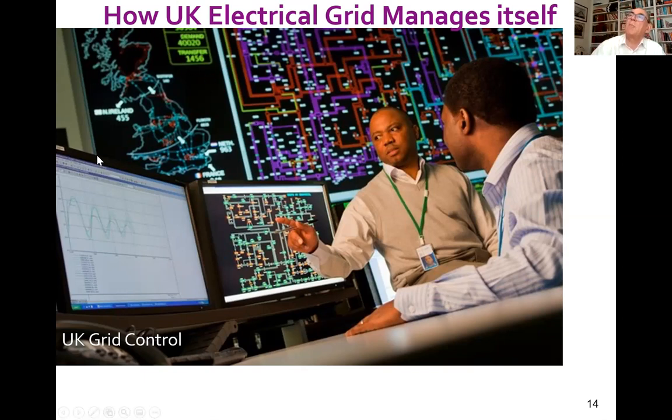And over here is a map showing Great Britain and the power flow. You can't read the number at the top there, but the green at the top is telling me the generation, and I can read it, and it's 39,000 megawatts, 39 gigawatts, being generated. But underneath in green, I think you can possibly read that, the demand is 40,000 megawatts. So the demand is bigger than the generation. So underneath you can see it says transfer 1,456.